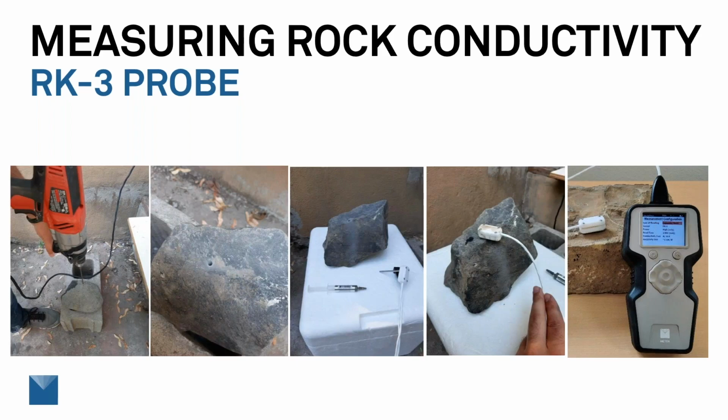needle. The point of this series of shots is to show you that it's pretty easy to find out the thermal conductivity of the rock that's in that soil profile. Now there's a minimum size of rock that you need to work with for this, since rock has a pretty high thermal conductivity. The radius of the material around the rock has to be at least a few centimeters so that the heat pulse will be contained within the sample.